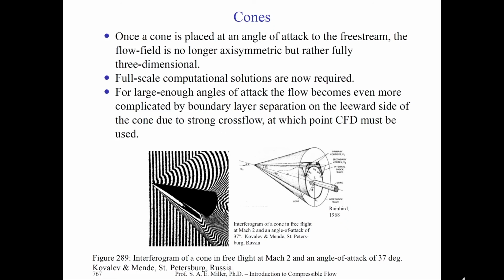And in this case, the flow field might be no longer axisymmetric. So if the angle of attack, or yaw, of the cone is 0, that means the cone is aligned exactly with the incoming flow. That is, the centerline axis of the cone, shown here, is exactly aligned with the incoming flow. Now, if we raise the angle of attack or lower it, or change the yaw angle in degrees of the vehicle, then of course the axis of the cone is no longer parallel with the incoming flow, and we can't use the classic tables which I just showed. In fact, there would be a whole other class of tables which will give us the solution as a function of azimuthal angle around the cone.